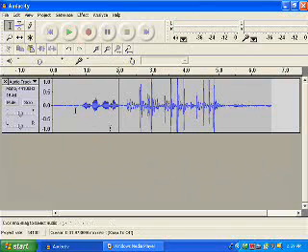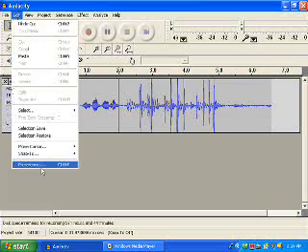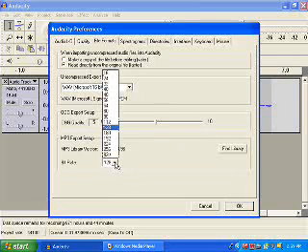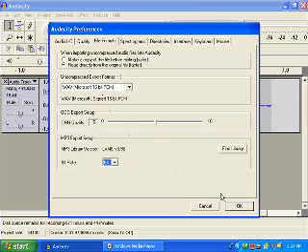To save the file as an MP3, open the Preferences again, choose the MP3 bitrate on the File Formats page. Generally, for audio recording, somewhere between 32 and 64 is good enough without making the file size too big. And it's that simple to create an audio, and completely for free.